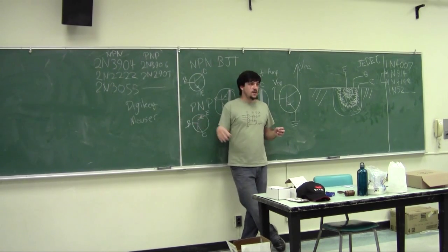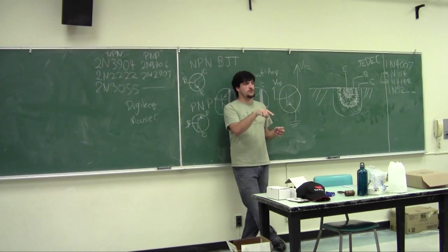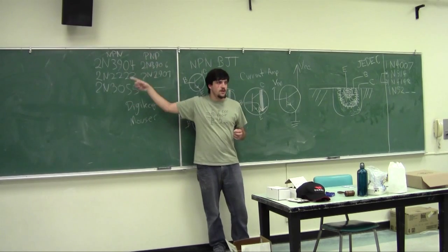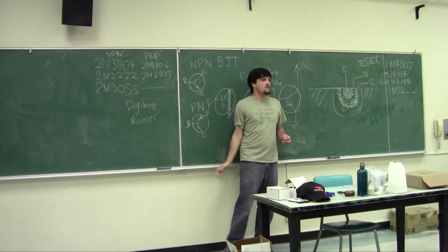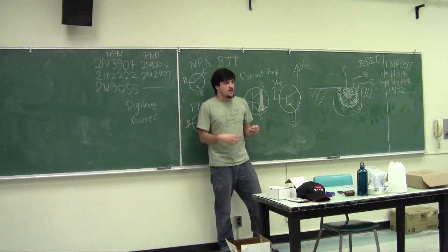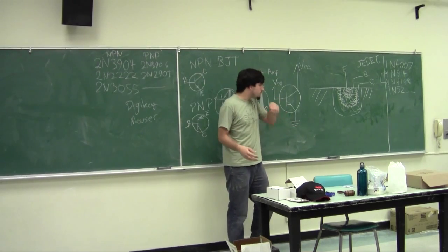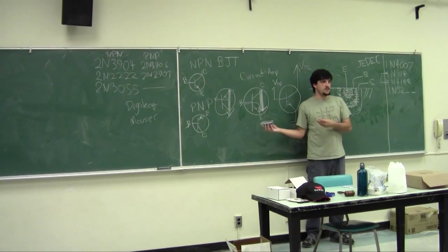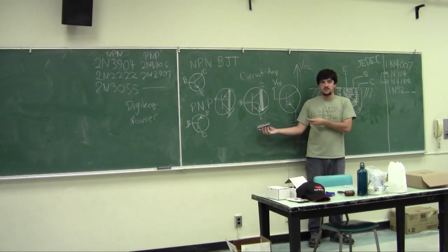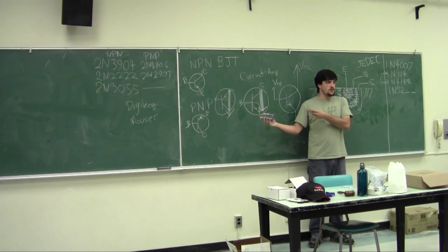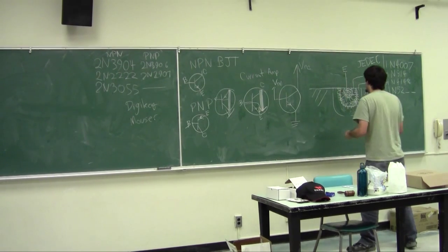So if you go to DigiKey's website and you go down to, I want a single transistor, it'll start asking you all sorts of questions about how much power you want to be able to deal with, and how much current you want, how much gain you have. And eventually it'll present you with this list of a couple hundred different types of transistors, and you'll just kind of pick the one that's cheapest. Right? So this is a bipolar transistor, which is the most traditional sort of transistor, and is actually fairly easy to make, and was one of the earlier technologies that they used to make semiconductors.